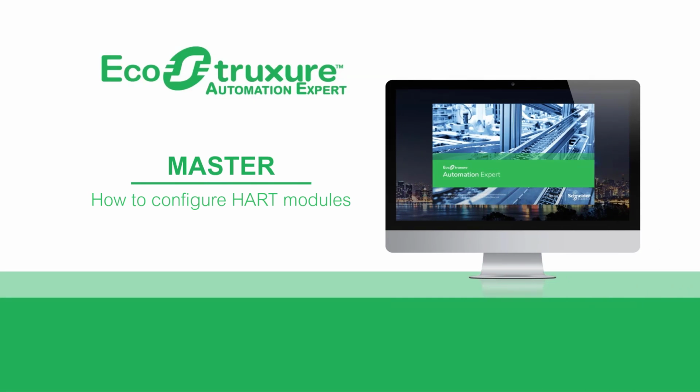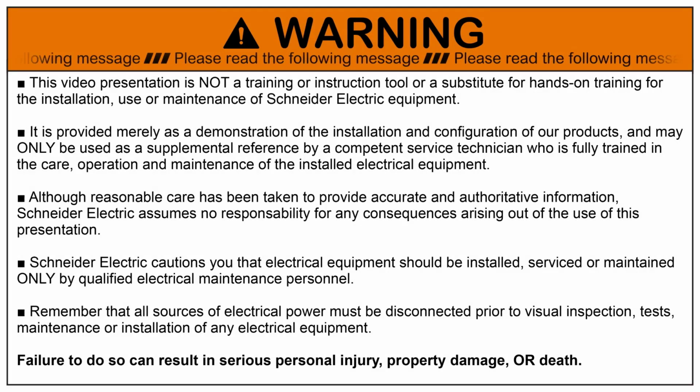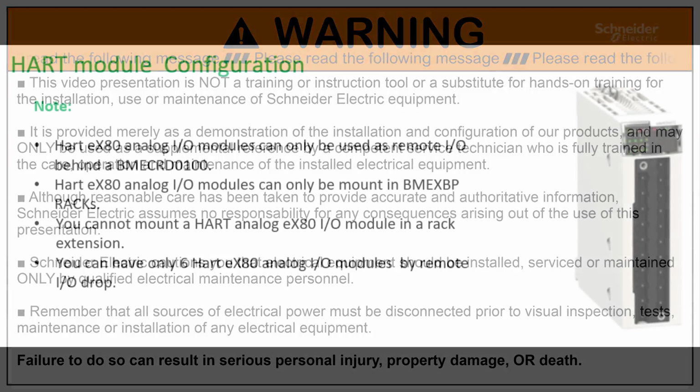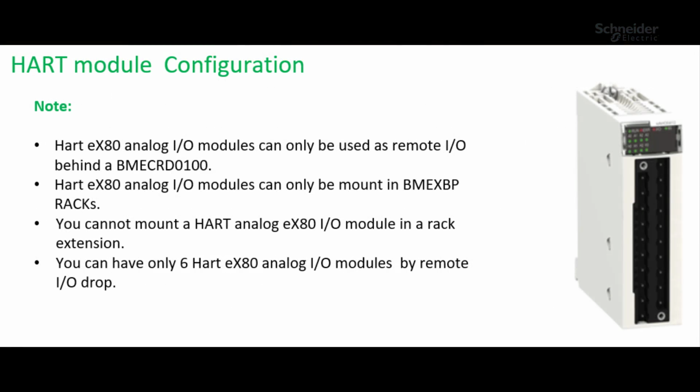Hello everyone, let's see how to configure HART modules. The Schneider Electric HART multiplexer serves as a gateway for HART-enabled field instruments. It allows you to view instrument status and data on web pages. It's a modular solution that supports up to 32 HART channels.